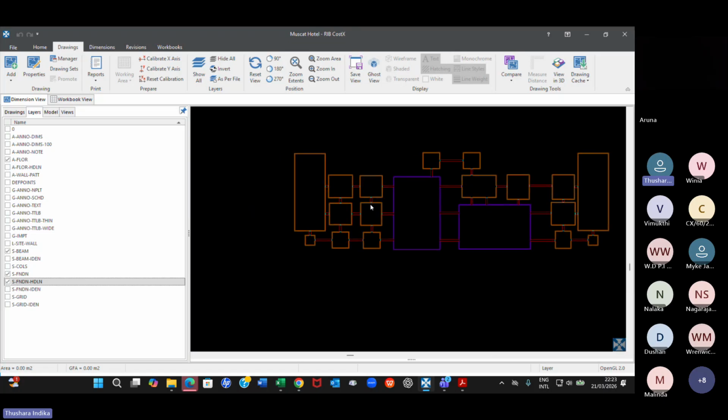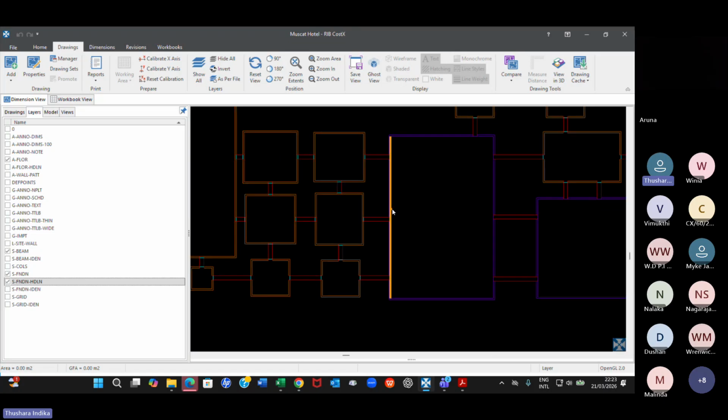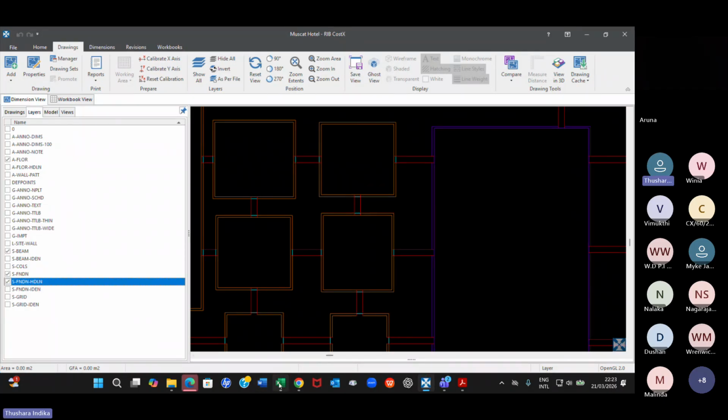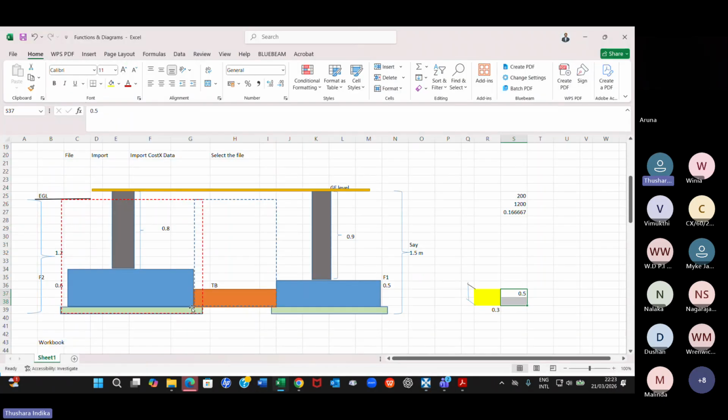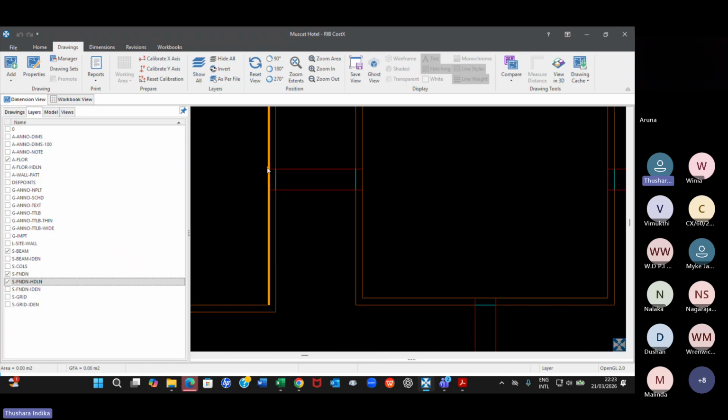Okay, can you get into this view first of all before we measure? And then it's a very easy thing to measure the tie beams, right? You can use even that function. What we are measuring is basically here, right? From internal to internal, right? On top of the PCC, the tie beam. So that means from here to here, okay?